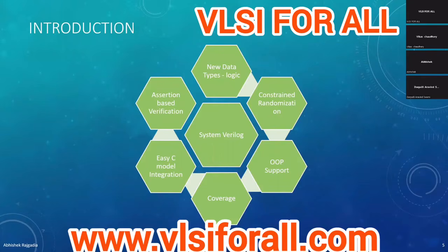We'll write some constraints in the test bench based on the specification of the design, and then we'll randomize. So the inputs will be generated within those constraints, because we do not want to verify a scenario in the design which will never occur in the real silicon. To make sure that everything is verified within real scenarios, we write constraints based on the specification. That is why constraint randomization is a very, very important feature.